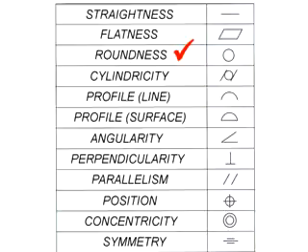If you want to know how circular a part is along its whole length, let's say like a pin, well then you're talking about cylindricity. If a line isn't round or part round, in other words, if it isn't an arc, but it isn't straight either, well then we call it profiled. The same applies to a surface. So we can have profile of a line or profile of a surface. These are often called irregular curves, and in the case of surfaces, they can be either two-dimensional or three-dimensional.